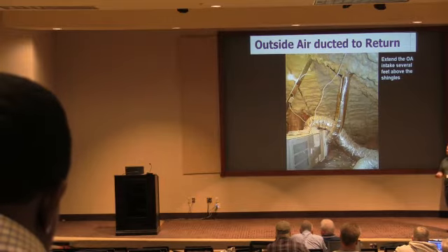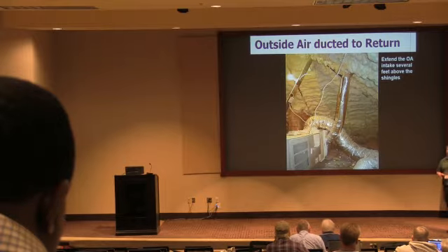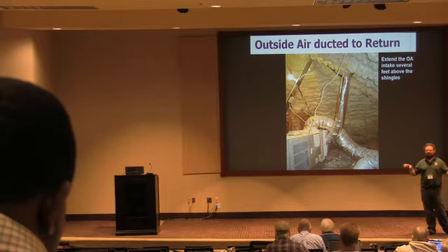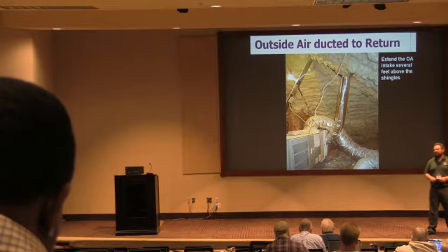Could you go into the soffit? Yeah, could run into the soffit, certainly. That's a good location for it. Lots of times we recommend to people they basically go out to a soffit or a porch overhang and draw outside air in from there. It's a good location.